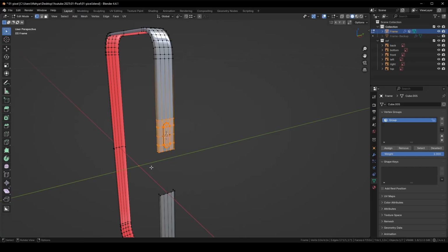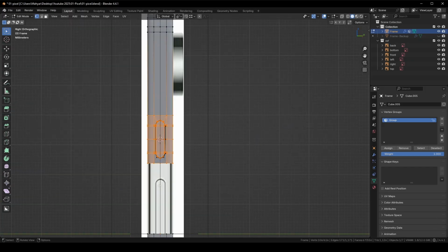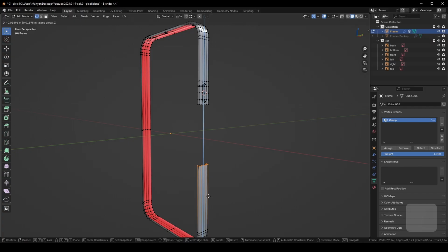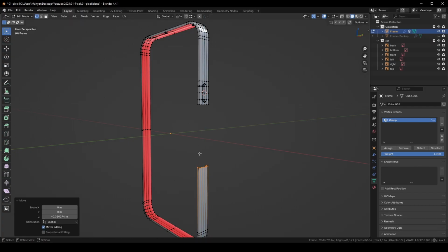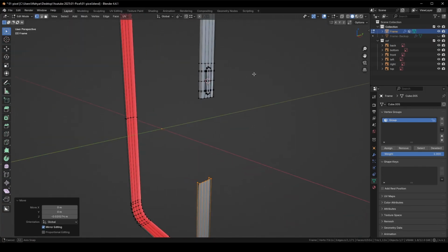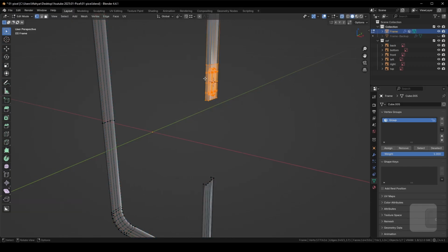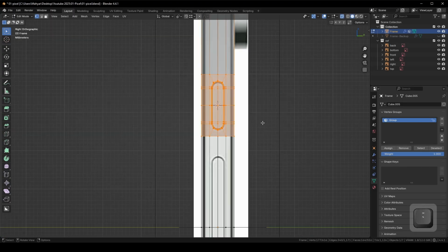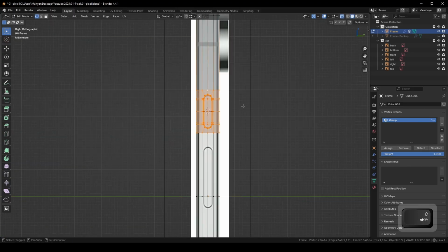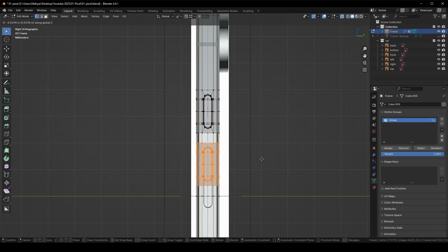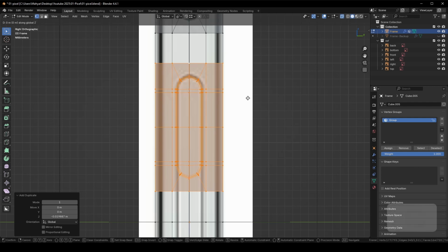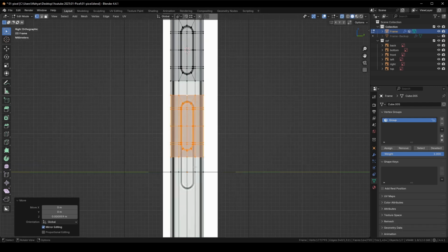Now repeat this process for this part. First I will slide this or move this, it doesn't matter because it's flat. Select this part, make sure to be in transparent mode to make sure all vertices are selected. Shift D, Z, match it with the volume rocker.